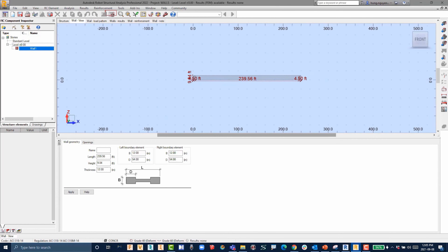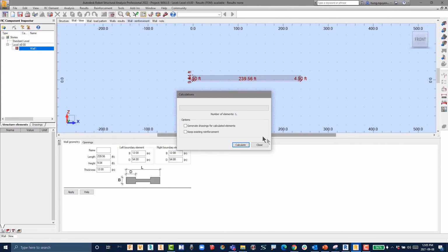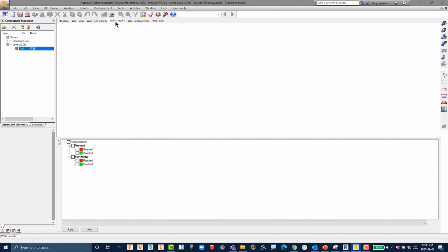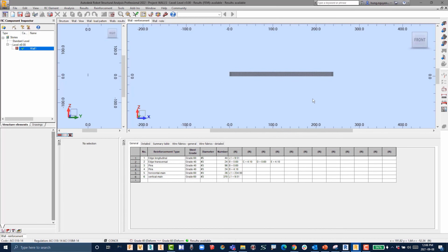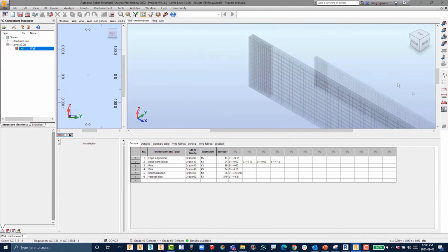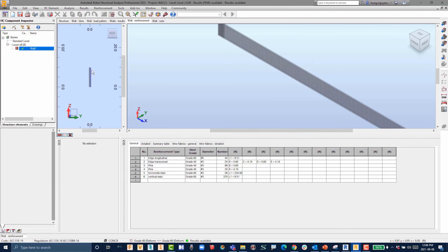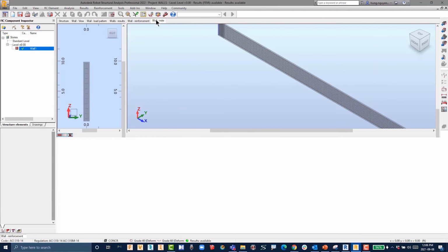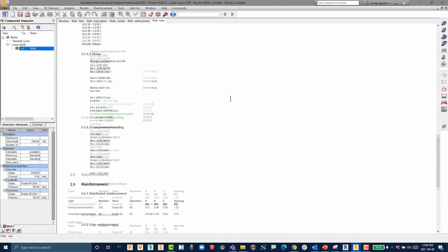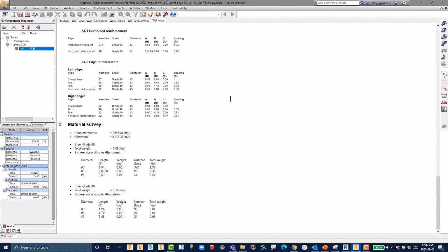With that wall selected, I will do a secondary calculation. Hit the calculation. It takes a bit of time, so now the results are coming out, and you could view that the rebar now is embedded inside the wall, and it has multiple views, and then you can also assign, if you want to override, you can always oversize a different diameter for it, and it has a full report on the wall node and so on, and it's very useful for a concrete designer.